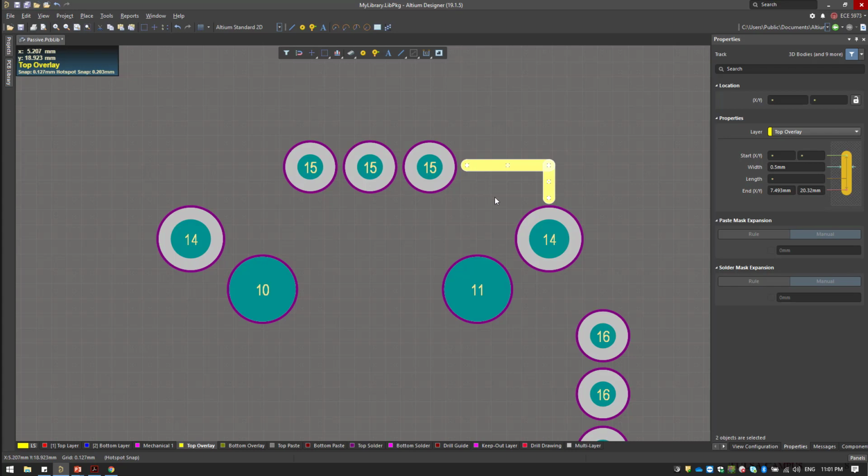So Control C, select this reference point because you need to flip it to the other side. Control V, and now, as you can see, it's in here. Now click on the X key. Basically the X key will flip in the X orientation. The Y key will flip in the Y orientation. So X, Y, as you can see, click, it's done.